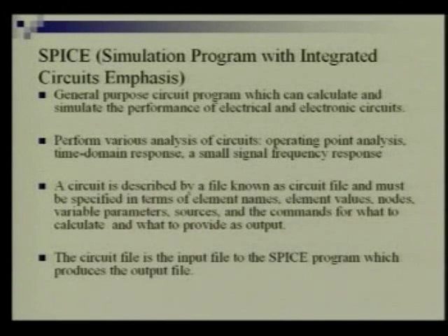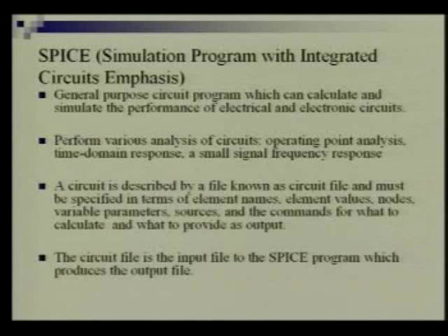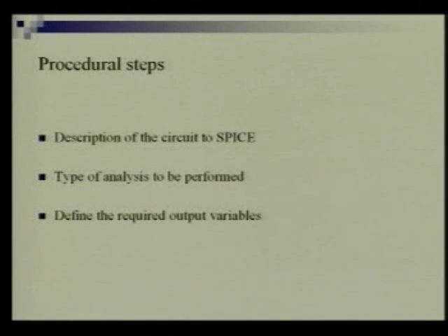The circuit file is the input file to the SPICE program, which produces the output file. How you are giving the problem, that these are the things, this is my problem, and now you simulate. Once you give the problem, then SPICE gives you all the output. Now the procedural steps: first, the description of the circuit to the SPICE. You will have to describe the circuit, that is, this is my circuit I would like to simulate.